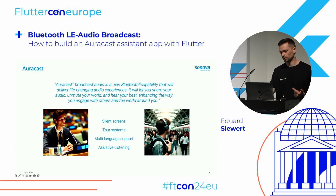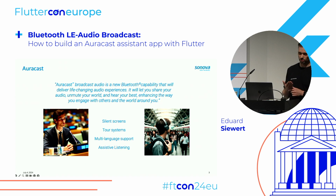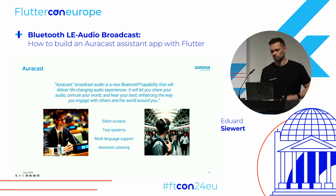And this is where the role of the Auracast assistant comes into play. So this is actually the third role in this network. You have your transmitter, you have the receiver, but now you have an Auracast assistant. And the task of the Auracast assistant is basically to display the available sources to the user and let them select a source and then provide this information to the receiver so that the receiver can synchronize to the stream of the transmitter.